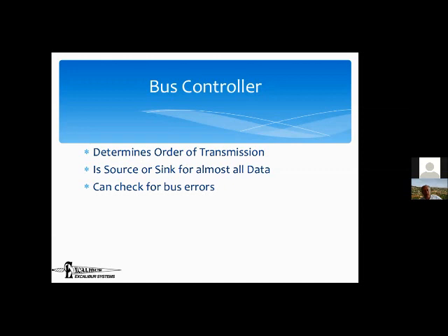Okay, so the real issue is if you have point-to-point communication, when a transmitter has something to transmit, he transmits immediately. As soon as the data is available, he sends it out. But if I've got 8 devices, right, in our case, the 4 missiles and the display and the trigger and whatnot, so I've got 8 devices, any of whom might have something to transmit at any time. Well, if they transmit at the same time and it's only a single wire, then they're going to crash into each other and nobody's going to be able to understand anything.